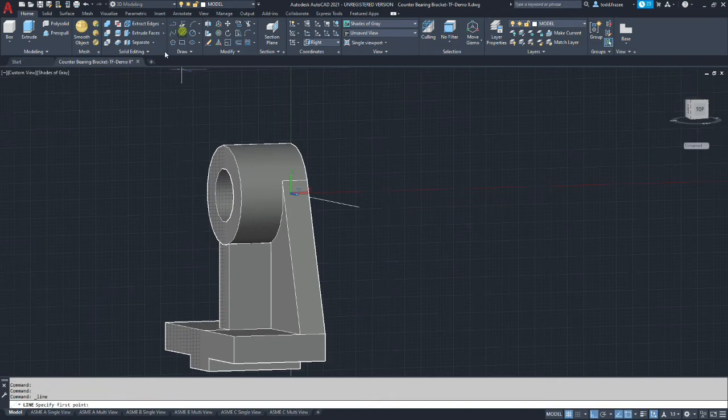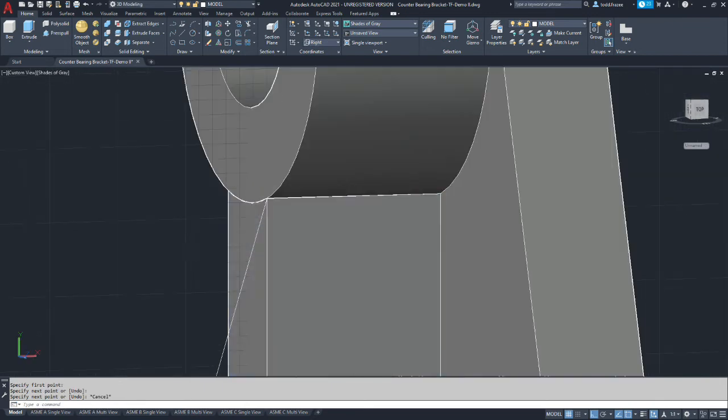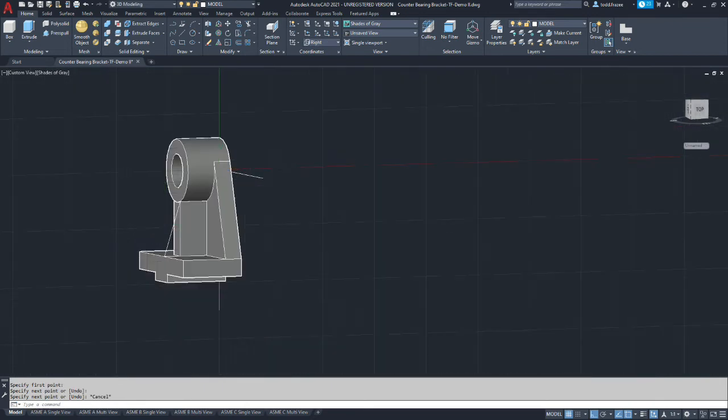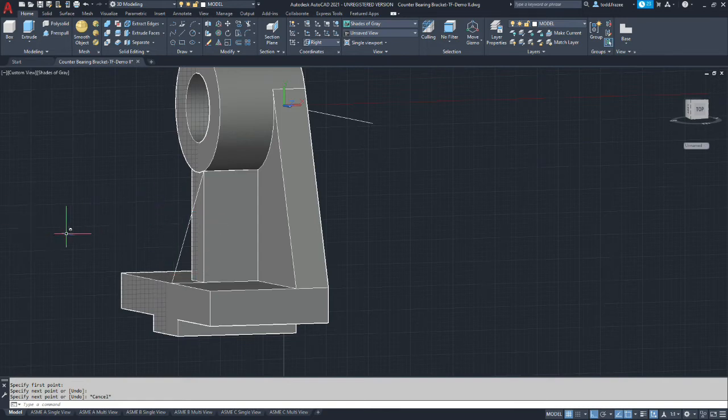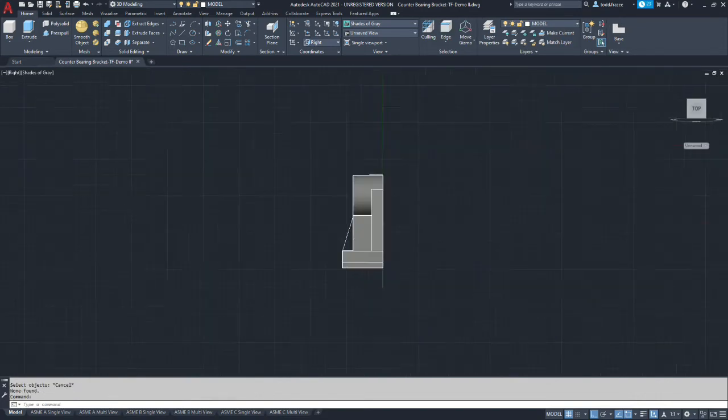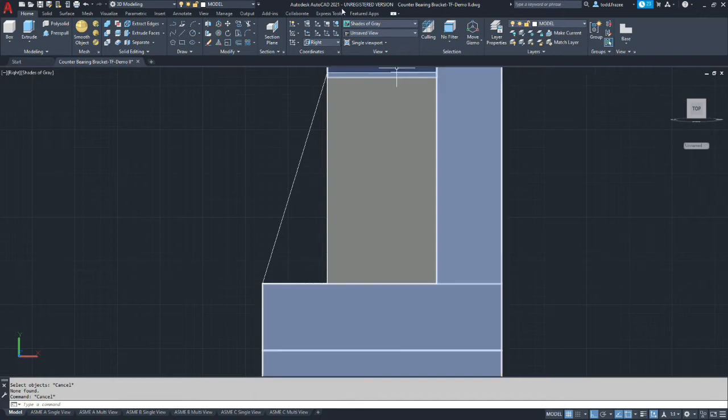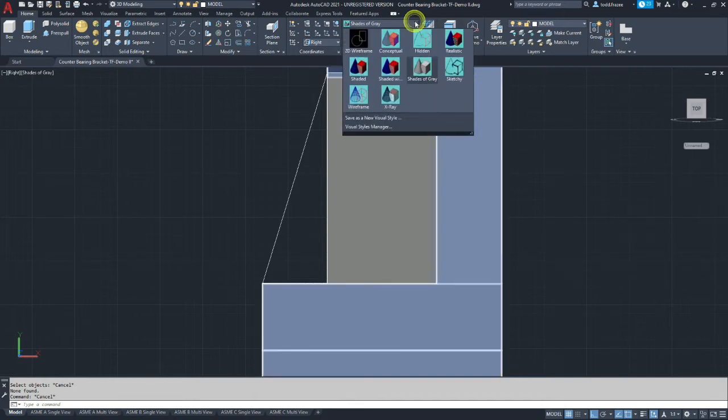Now let's connect our two legs of our triangle to make a hypotenuse. Ortho will give you a little fit there when you're trying that, but it'll still let you do that. So this is a triangular region that'll be used for another extrusion. Might help to look at it straight on. Alright, we're going to go to wireframe.